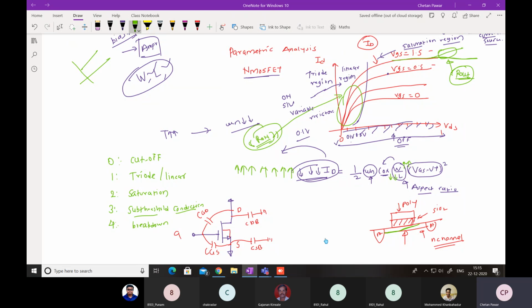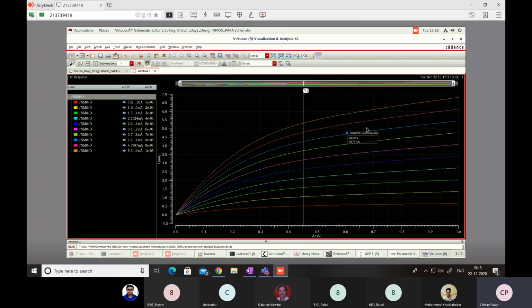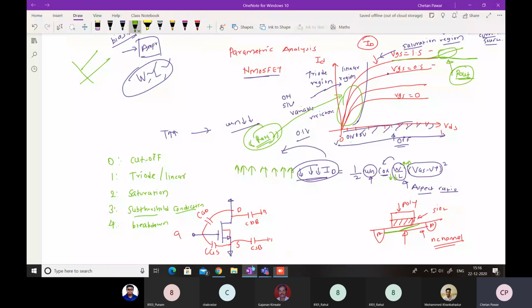Generally, if I'm designing a chip for a microprocessor, as you have seen in the inverter section, we take one PMOS and NMOS, right? In our microprocessor there are different sections like RAM, ROM, and other control units. All these units are sometimes designed prior or available in the library. Such designs are called standard cells.